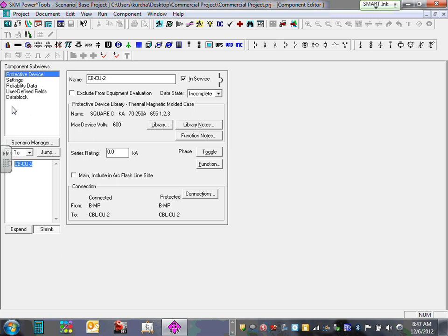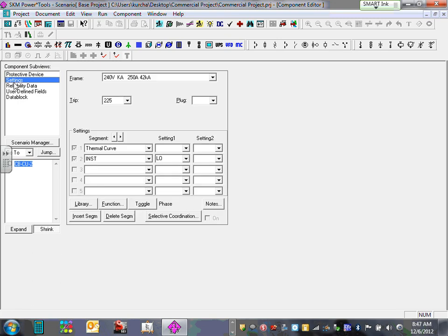Double click on the last chiller, same circuit breaker. What was the last chiller? Over 60. Okay, now this guy, I'm going to go all the way to 100. And do I have 60? I'm stuck with 70. It is what it is. You can change it to a different breaker. Well, in real life, yes. You would go back and change it to a circuit breaker that can give you 60.